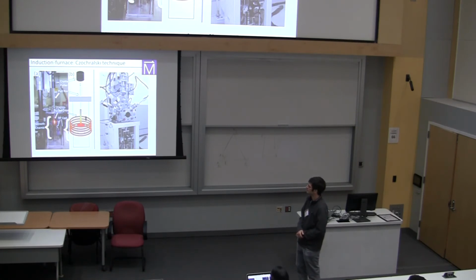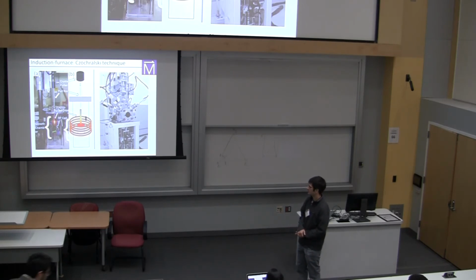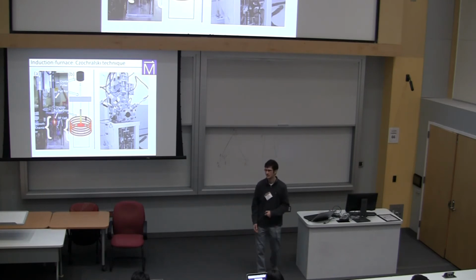And the point that I want to make here is that the induction furnace gives you a very nice way to accomplish this sort of situation on the cheap, right? So these types of apparatuses are really nice. They're wonderful. You can make beautiful crystals in them. They're also extremely expensive. With a little bit of ingenuity and accepting that it may not be perfect, you can build up a nice Czochralski crystal puller within an induction furnace as well. So if you become an assistant professor someday and you don't have a lot of money, you can think about doing it this way.